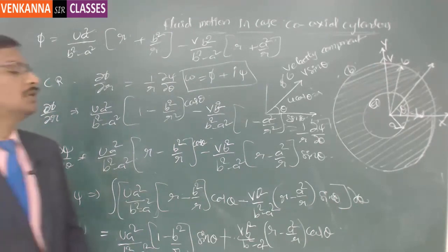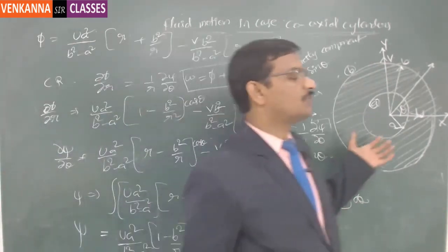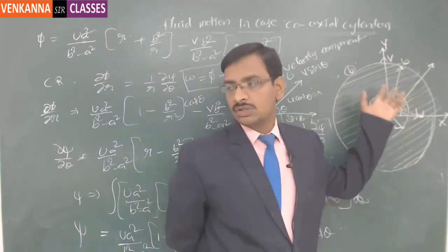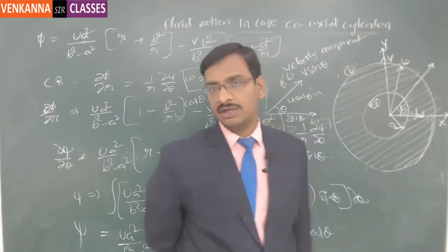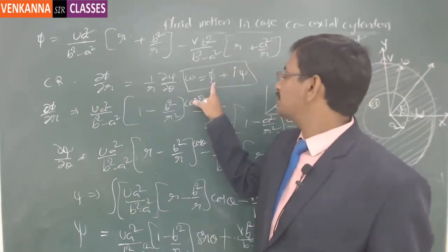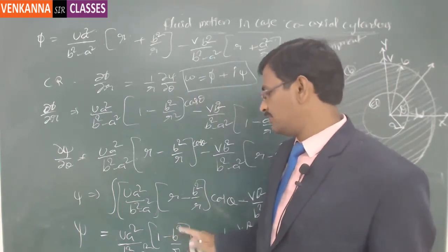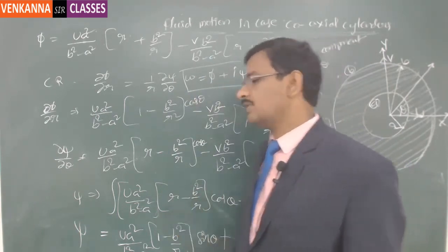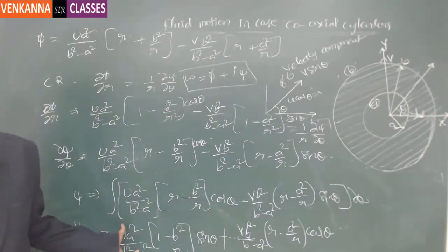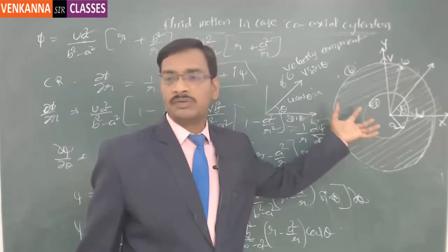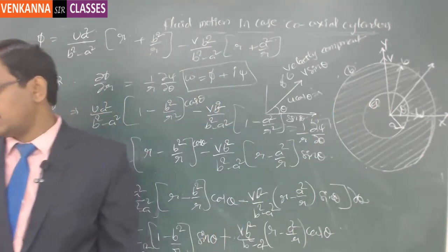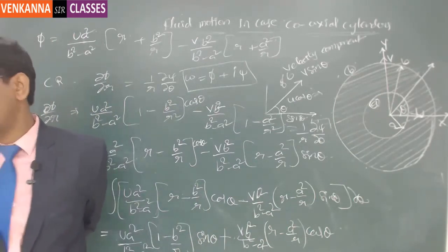So this is how you will find it in the case of motion of two different cylinders moving perpendicular to each other. The fluid is getting distributed in such a manner. The equation of the potential is represented by phi and the streamlines equation is psi. So this is the stream function. For a constant value of the stream function, it represents a streamline, so how the fluid is moving, the equation of that will be this. Clear? At any instant of theta, you can find the direction of the fluid there.